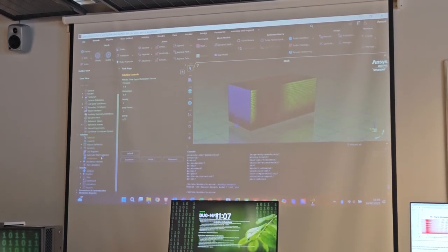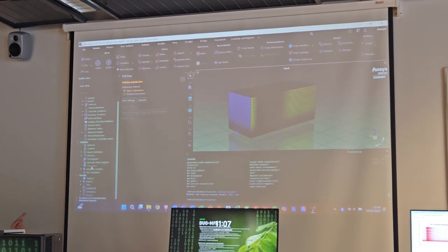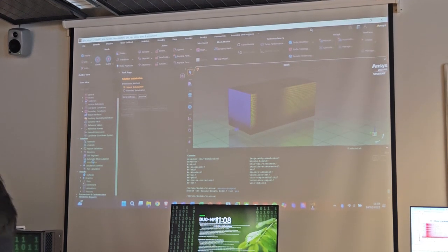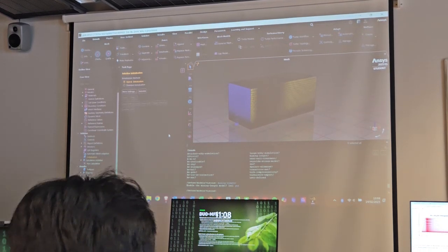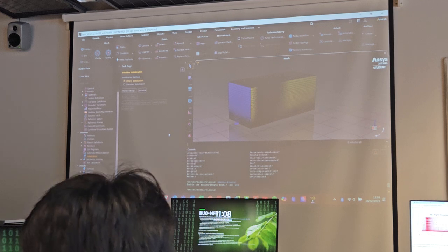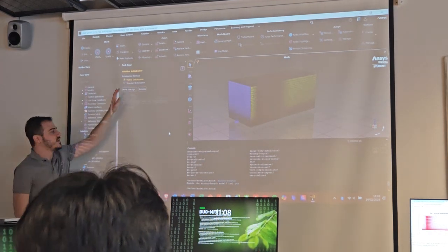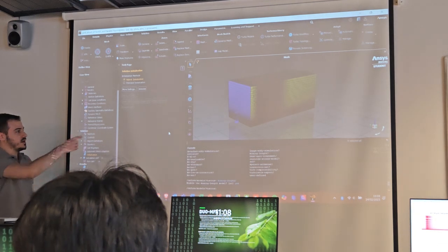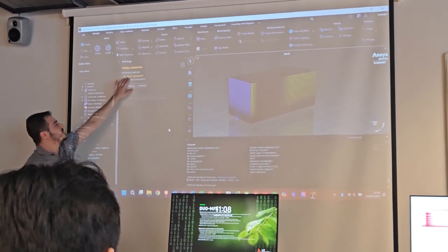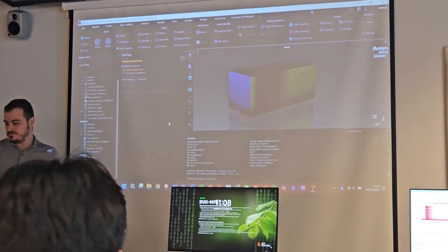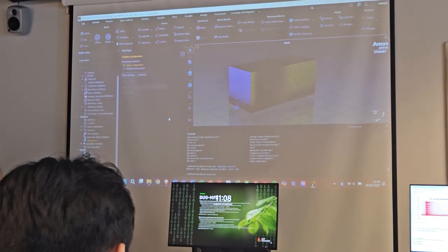Okay, so we have done everything. So the first thing now that we need is initialization. On the left, we can double click on this. We need to initialize the flow variables in the domain. We can do this in two ways. There is a hybrid initialization that is kind of automatic based on the boundary conditions that you have set. The solver kind of initializes it like a black box. You just don't see what's happening.